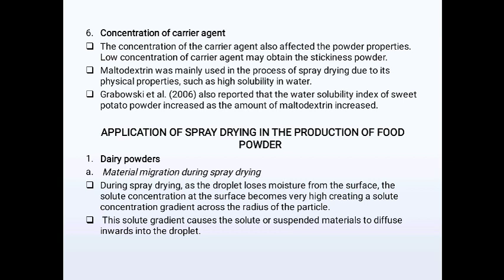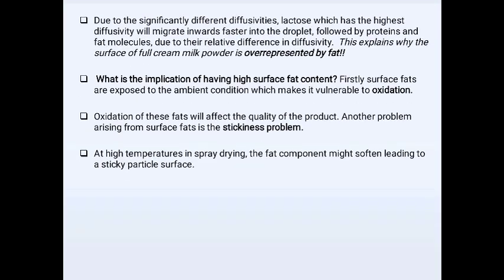Dairy powders. Material migration during spray drying. During spray drying, as the droplet loses moisture from the surface, the solute concentration at the surface becomes very high, creating a solute concentration gradient across the radius of the particle. This solute gradient causes the solute or suspended materials to diffuse inwards into the droplet.